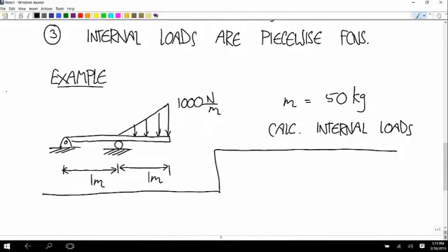Okay, well, the first thing we're going to have to do is calculate the external loads. We've had ones before where we didn't have to calculate the external loads at the joints, but that was only when we had a fixed joint at the right edge, and that's because we never had a cut. Our cut never represented that point, so it never showed up. If you have any joints that aren't at the far right end, then you have to do that first.